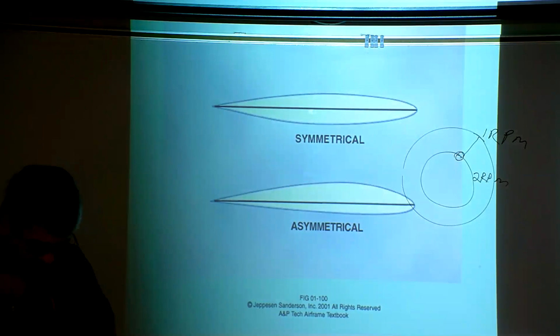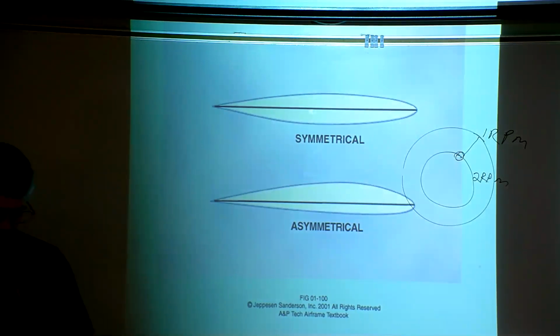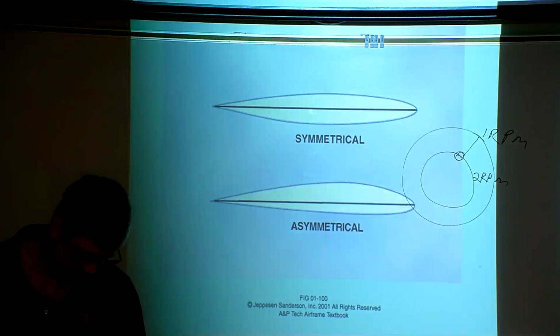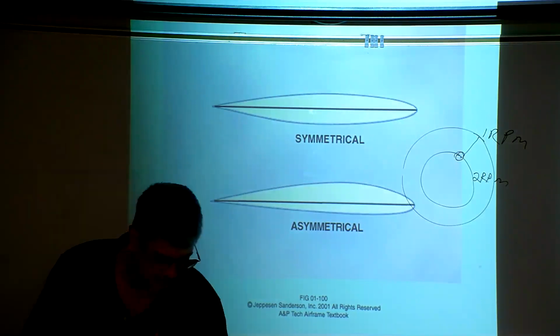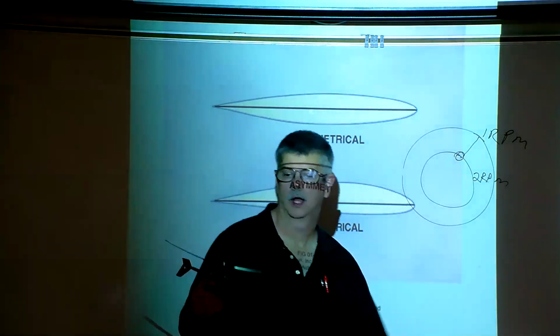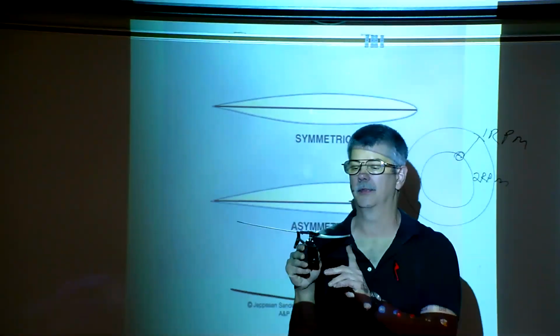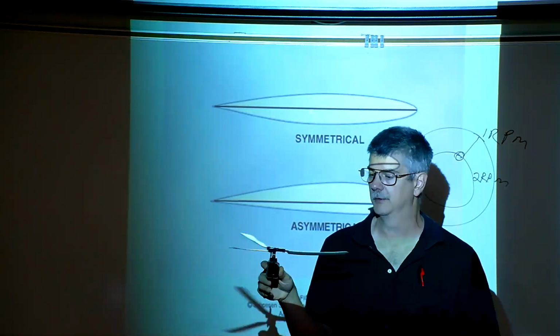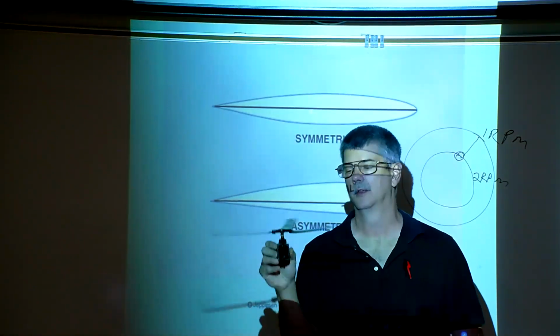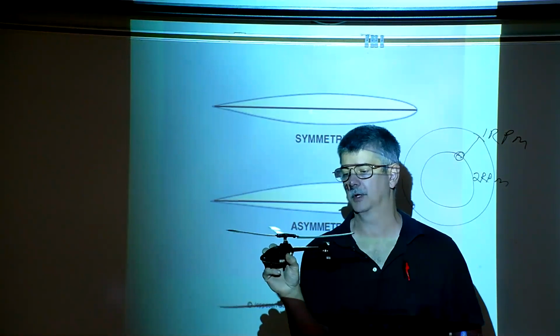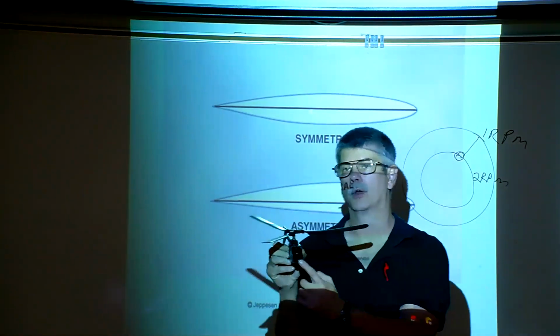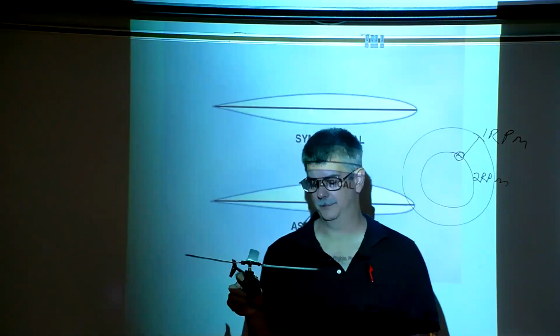All right. We then went into the helicopter flight conditions, hovering flight. As I said, in hovering flight, the big problem was torque on the helicopter. As we spin the rotor blades counterclockwise, the body of the helicopter wants to turn clockwise, or the nose wants to go to the right.